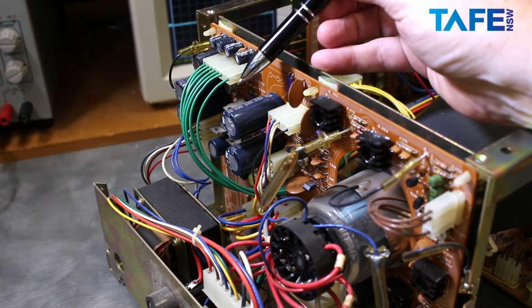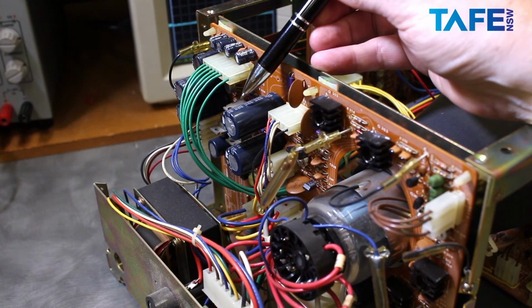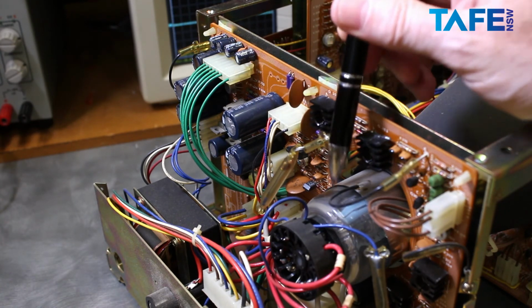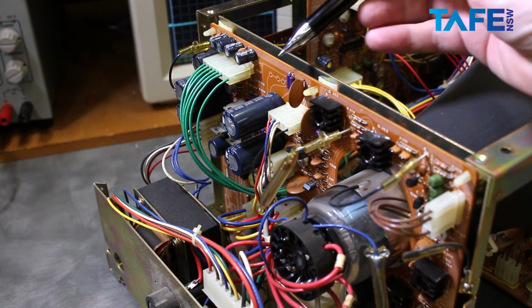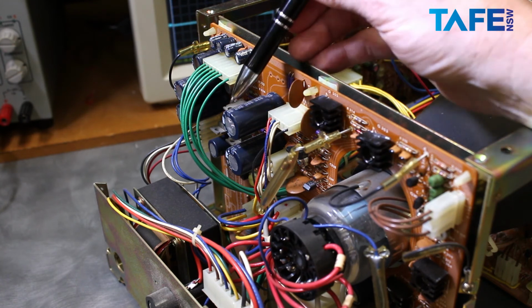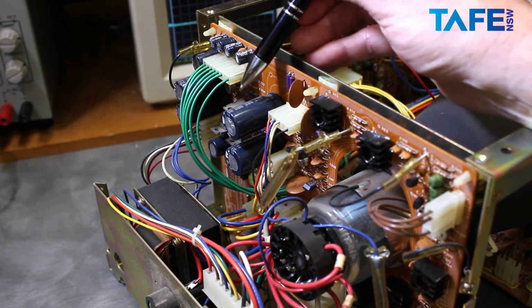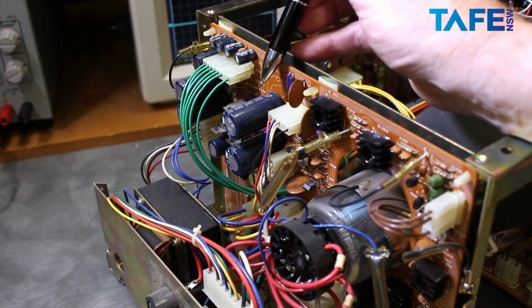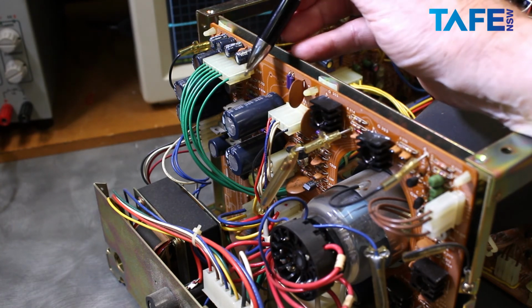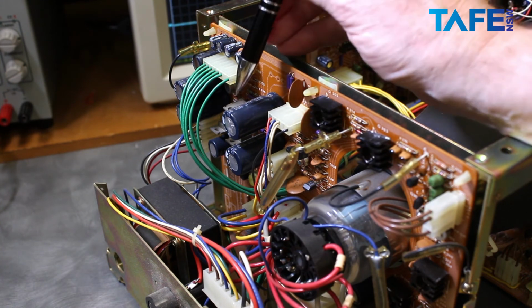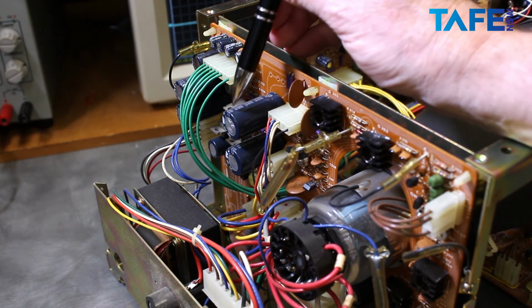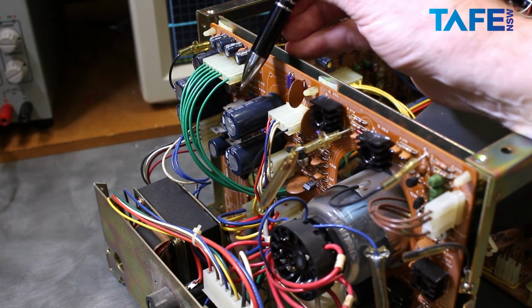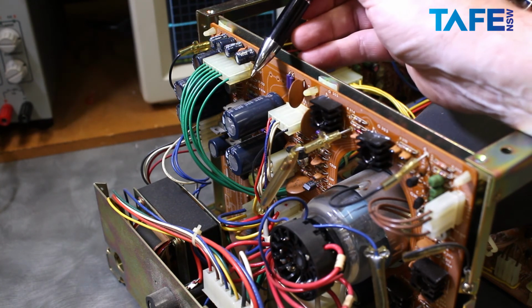I have here some capacitors in the back of this old oscilloscope. It's an old cathode ray tube oscilloscope, pretty well obsolete these days. These capacitors are possibly dried out. They are ELNA brand, E-L-N-A, made in Japan, and although they date back to 1980, they'd be touch and go. They might still be okay. I have seen that particular brand last a long time.